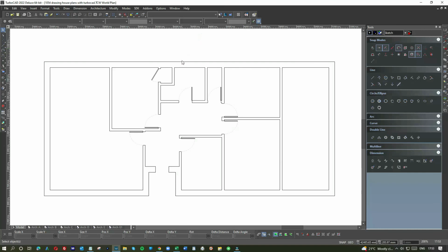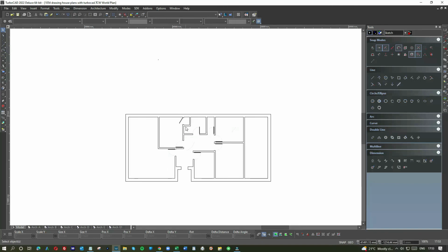Now, you've just successfully watched me create a 3-bedroom bungalow from PDF, and I can tell you now it's pretty accurate. Remember when I scaled it, it was only out about 1 mil. So the walls are the correct thickness for a new build, 330. For a standard new build, of course you can make it thicker if you want to do something else. In any case, if you're making a new modern bungalow, you'd make it a bit bigger. All these rooms would be a bit bigger, and you certainly wouldn't lay it out like this.